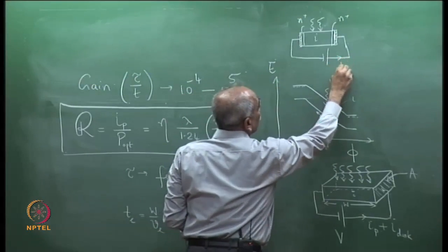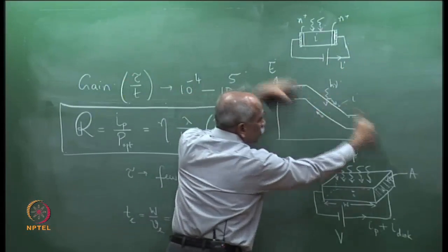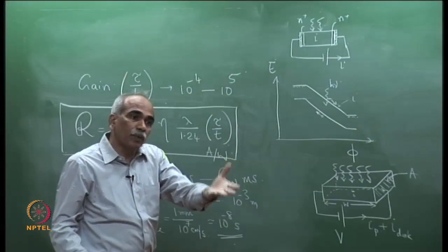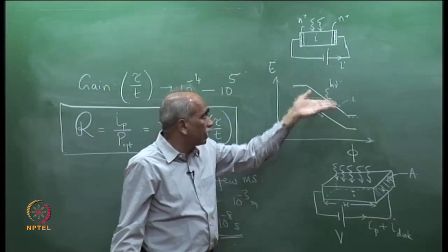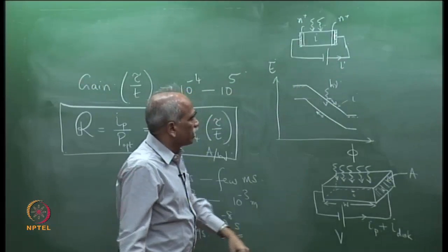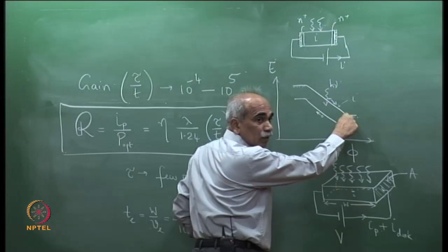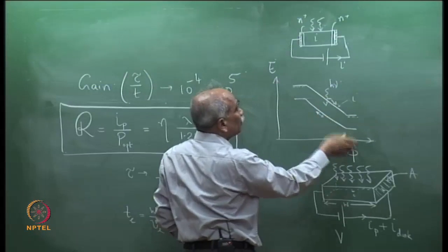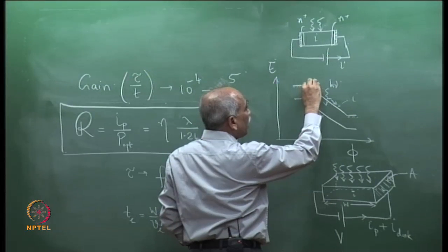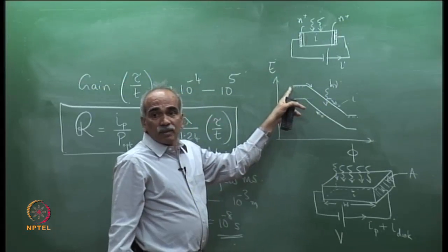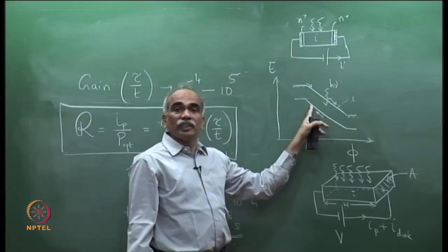There is a current I here in the external circuit because of charge carriers moving. We have discussed this in the last class before impulse response. By Ramo's theorem, there is a current in the external circuit. When the electron is collected here, then to maintain charge neutrality, a second electron is released from this contact, because there is only one hole which is moving.